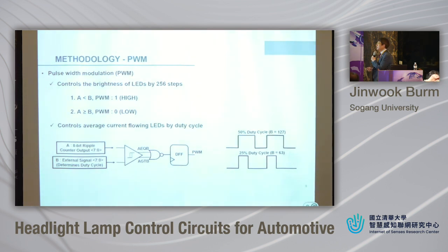We use the D flip-flop to maintain the pulse width precisely. We use 100 megahertz for the clock. There are two examples in the design stage, high code and low code. This high code means brighter light, and this is the dim light.